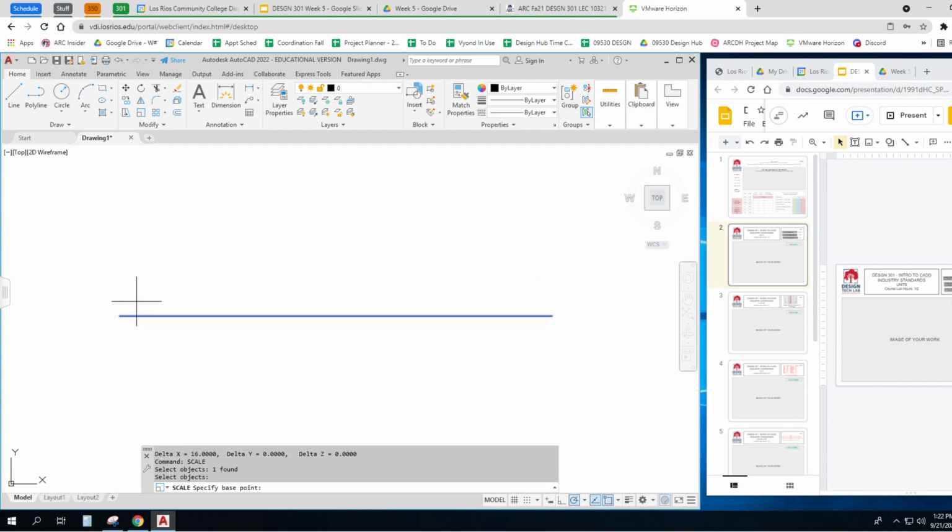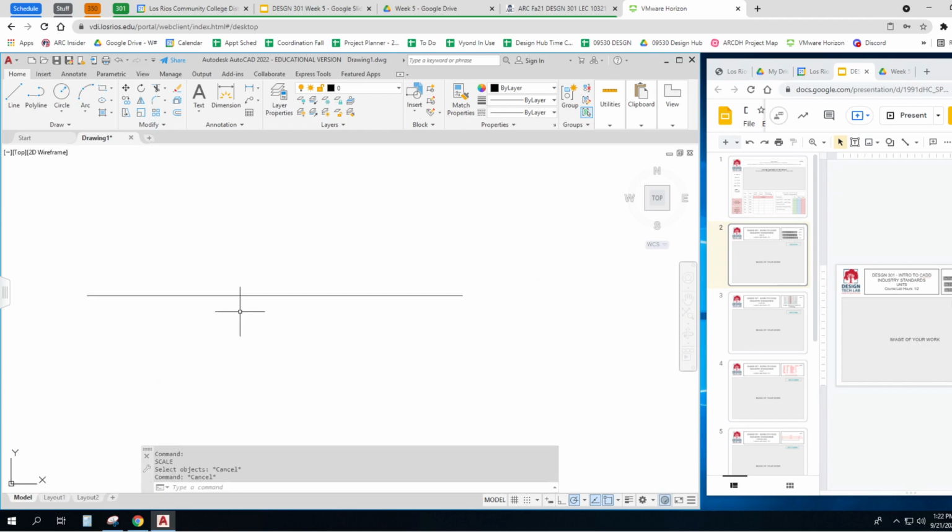And this is really important to know. That's my base point. 1 divided by 12. Now that I'm talking about feet, I have to actually convert my drawing from inches to feet. AutoCAD does not do that for you. Other programs do. Inventor does. Fusion does. I think SolidWorks does. AutoCAD does not. I drew it 16 long, and if I change the units, it just thinks that I really meant 16 feet. So I have to change that to make it 1/12 as long.